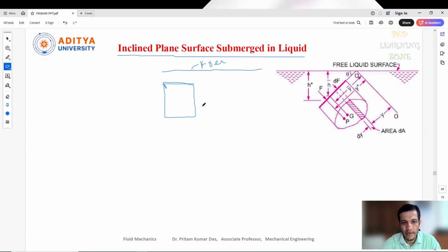Or we can consider any kind of object which is placed vertical to this free surface, and we have considered some small strip, a small area, on that. Similarly here also you can consider. Here what I mean to say is this plane surface is perpendicular to the liquid surface. That means it is vertically placed inside the liquid, and the liquid is in the rest condition, that needs to be remembered. And here we have taken the center of gravity point and the pressure point on this.